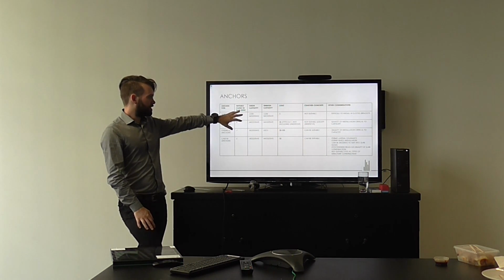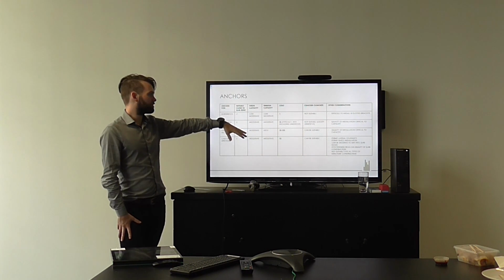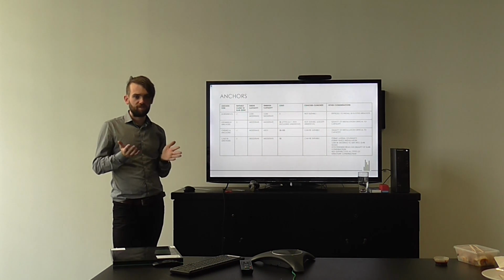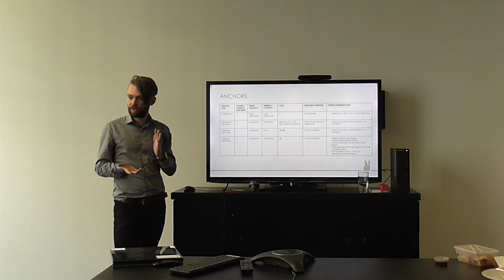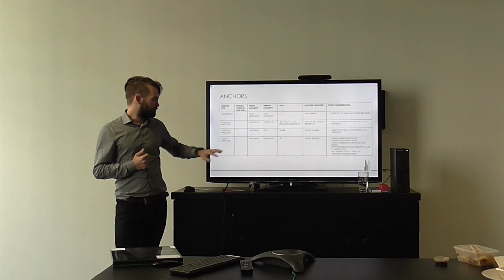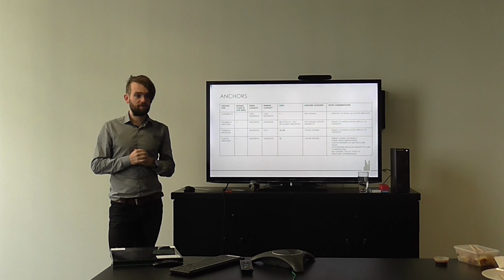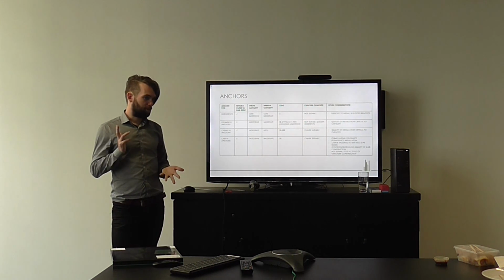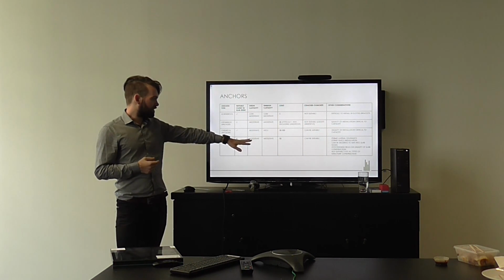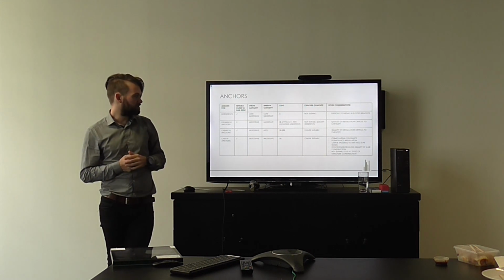In terms of shear capacity and tension capacity, they tend to step up as they do with their associated cost. The screw bolt, which I showed first off, has low to moderate strength. Expansion anchors are around about the same, but because there's a little bit more going on with them, they tend to be a little bit more expensive. Chemical anchors are reasonable in shear. They have quite high tensile strength, which is good, but they also come with a bit of a price tag depending on which product you end up using. And the casting anchors, I would probably deem moderate strength in both situations, and price.